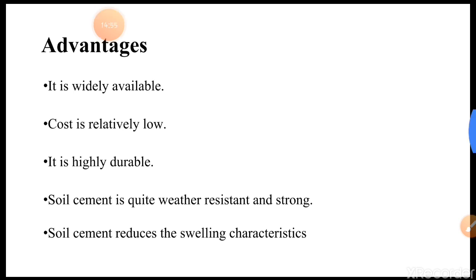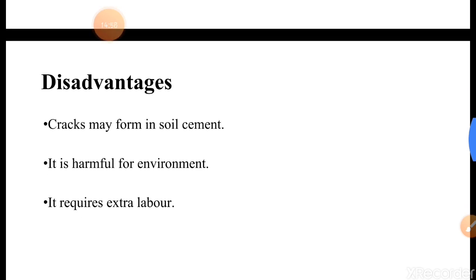As we have seen the advantages, there will also be some disadvantages. Those disadvantages are that cracks may form in soil cement. If the soil cement is not properly cured for extreme heat conditions, definitely it's going to crack. And if it cracks, there are chances that water may penetrate inside the soil.